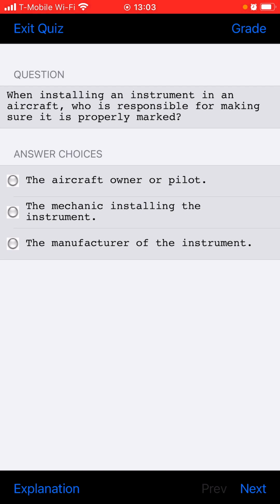What effect does underinflation have on aircraft tires? Internal heat damage, possibly leading to premature tire failure and more tread wear on the shoulders than in the center.